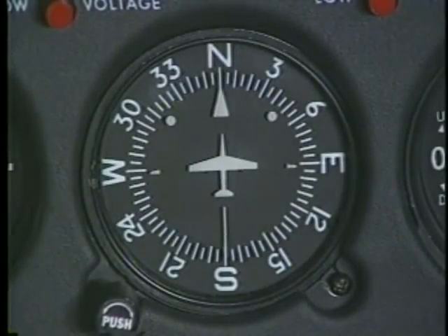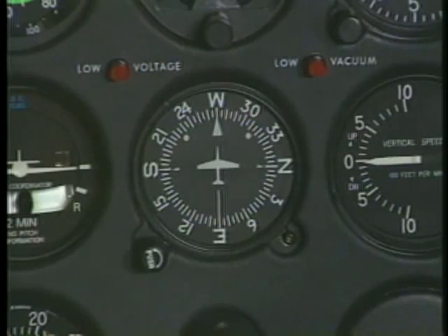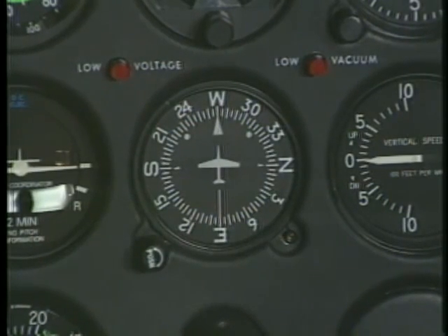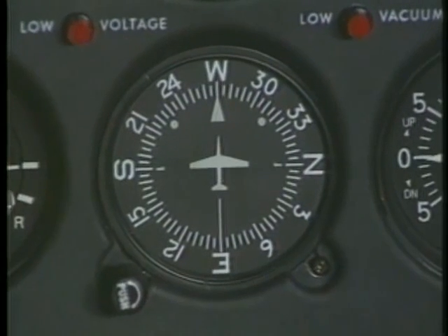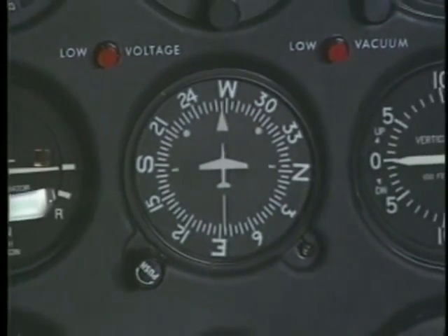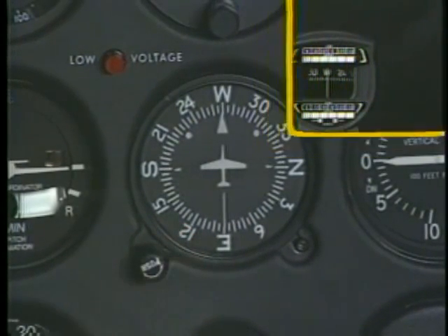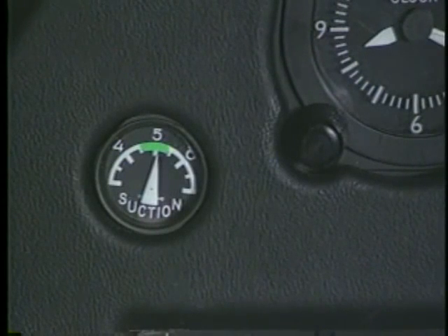Now let's review the heading indicator. The spinning gyro in the heading indicator is aligned with the vertical plane, allowing it to sense any changes in the airplane's vertical axis. The heading indicator is very susceptible to gyroscopic precession. As you maneuver the airplane, the external forces acting on the gyro cause the heading to drift very slowly. In this case, it has drifted 5 degrees. For this reason, you need to periodically realign it with the magnetic compass. Because the operation of the attitude and heading indicators relies on vacuum pressure, be sure to include the vacuum indications in your scan.